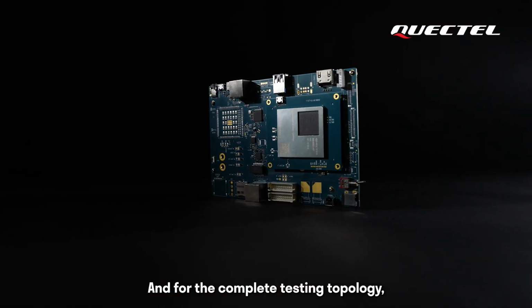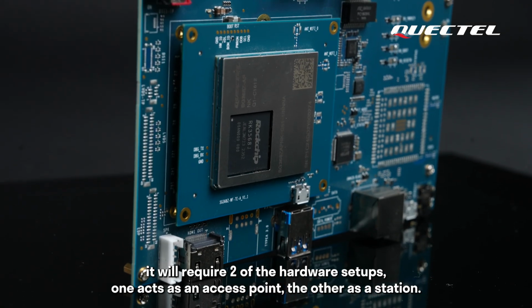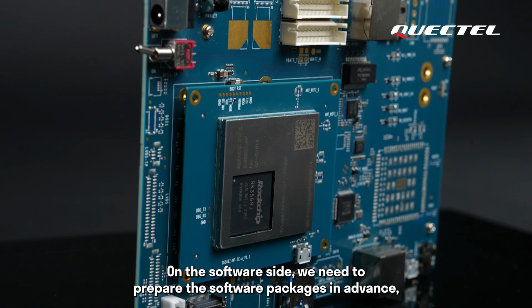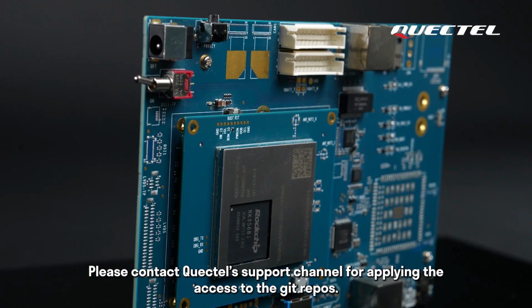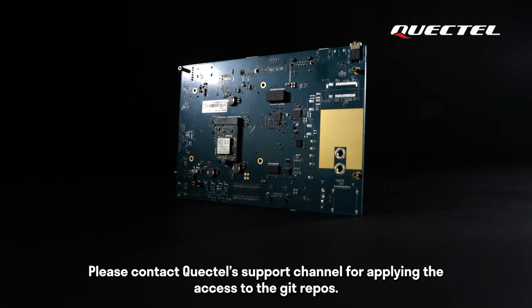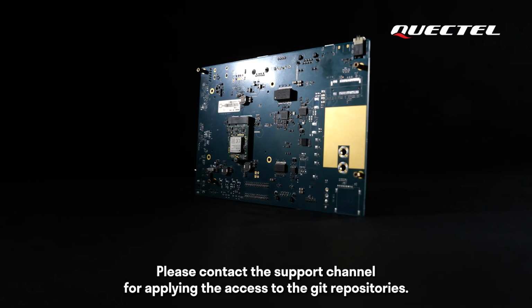And for the complete testing topology, it will require 2 of the hardware setups. One acts as access point and the other as station. On the software side, we need to prepare the software packages in advance for both the FGH100M module and the RK3568 as the MCU. Please contact Quectel support channel for applying the access to the Git repositories.